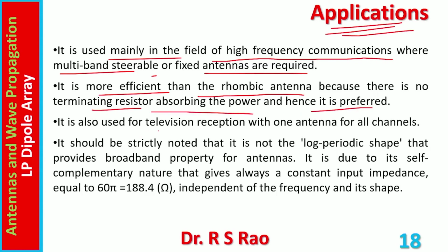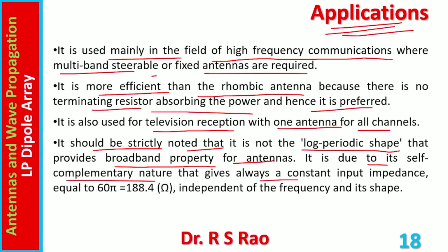It is also used for television reception with one antenna for all channels. It should be strictly noted that it is not the log periodic shape that provides the broadband property for antennas. It is due to its self-complementary nature that gives always a constant input impedance equal to 60 pi, 188.4 ohms, independent of frequency and its shape.